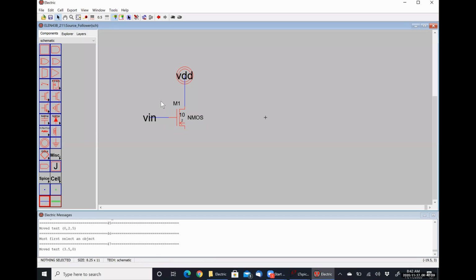Dr. Hartman, does a guard ring always have like 0 potential? Only if we connect it to ground. Okay. And the guard ring around our PMOSs will only have a potential of 5 volts if we connect it to VDD. Otherwise, it's effectively a floating potential, whatever the source is at when we've tied them to the source. Okay.